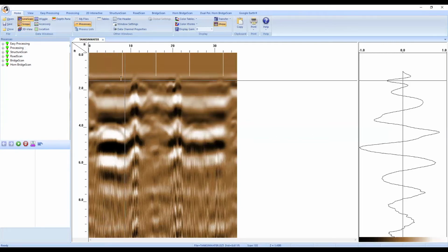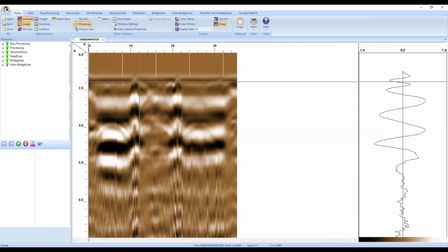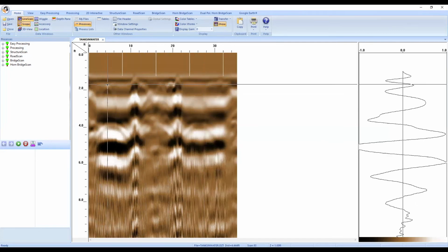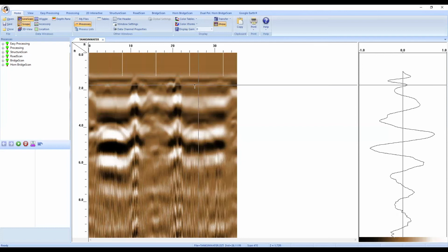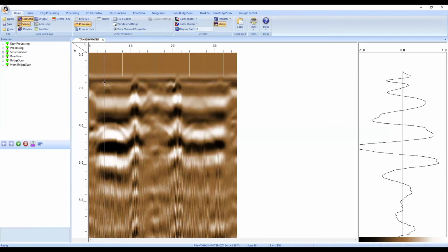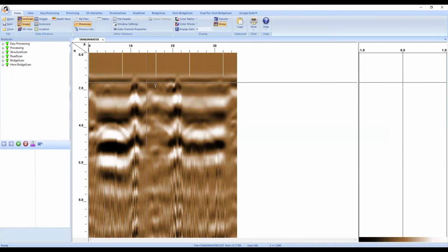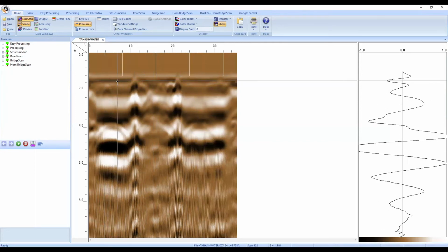And what we need to find in our data is a reflection from the antenna that is not in the ringing area. So if we're doing this out in the field, we would just go to a part of the file that doesn't have ringing in it and look for two positive amplitude reflections or two negative amplitude reflections that might be around a real reflection received by the antenna.